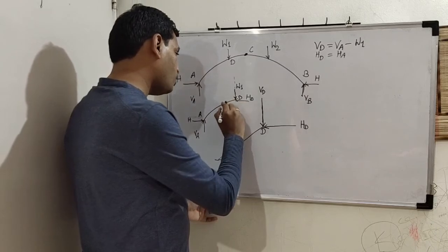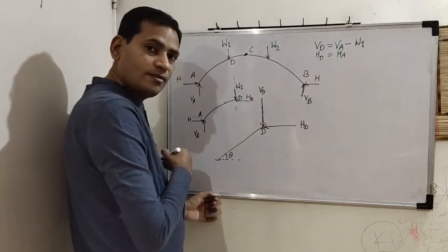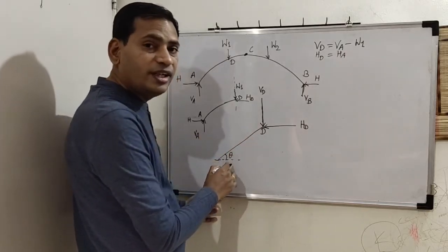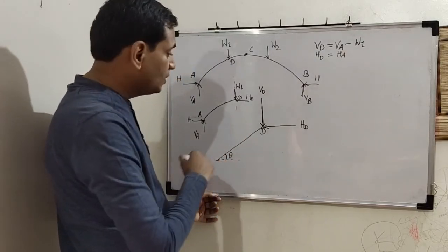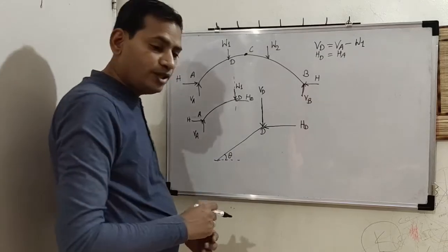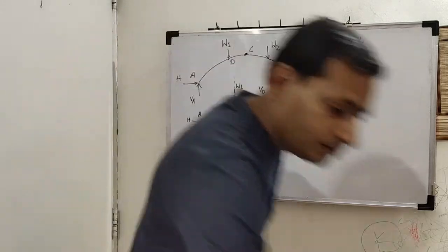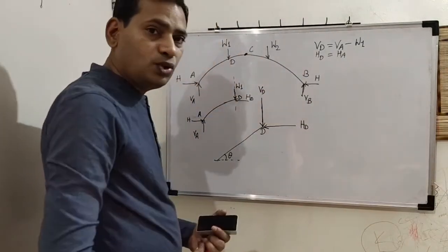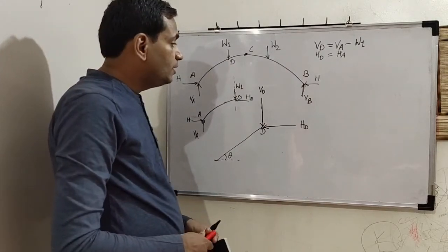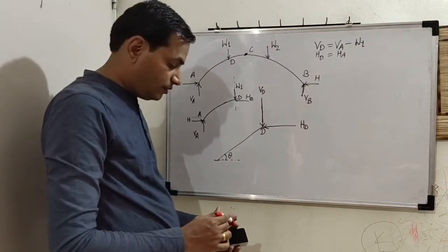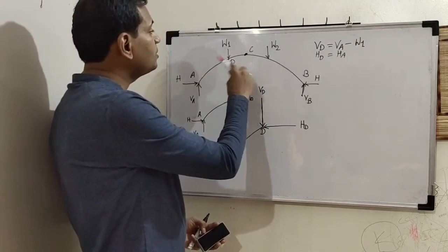Now on point D I have drawn a tangent. Okay. This is the tangent whose inclination with the horizontal is theta. The angle of this tangent with the horizontal is theta. What I am going to do now is resolve these two reactions. Correct? So we need two components in this, radial and tangential shear. Okay, because the diagram is curved.